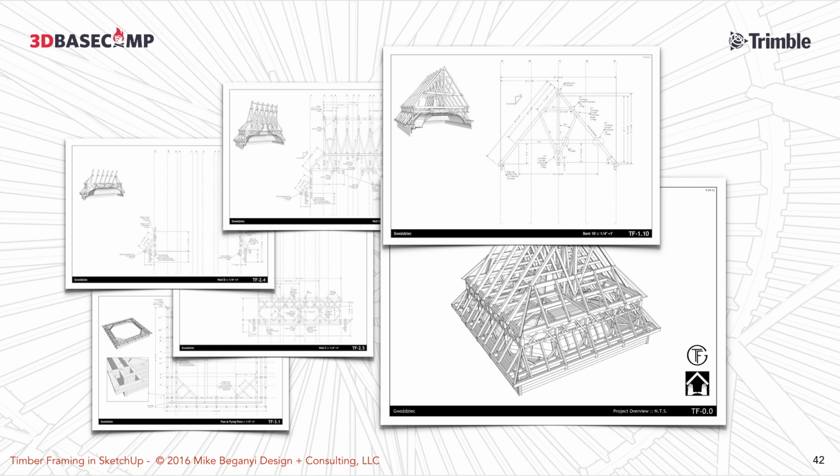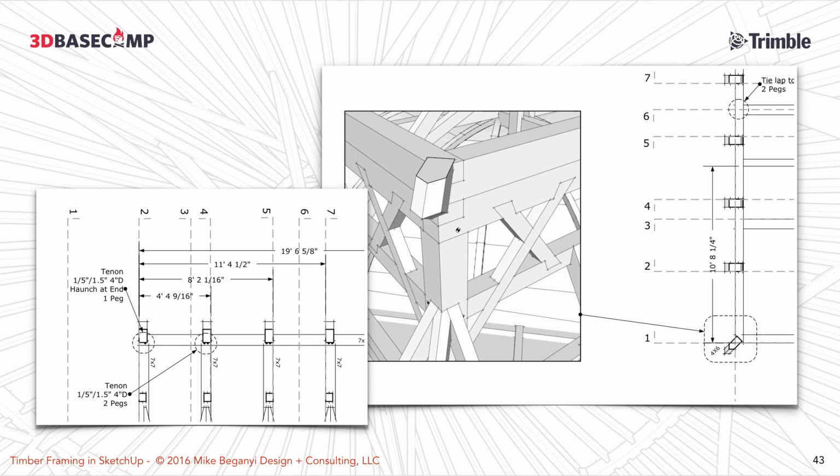So each section of this building had a cut through it, and then I would detail that, and I would also pull off small 3Ds and stuff them into the corner of my main drawing so that you could see how the rafter dropped on the corner. Each one of those little numbers there, 1, 2, 3, 4, 5, 6, 7, I think there were 12 bents going one way and 12 going the other way, because this whole thing is an intersecting roof. Each one of those represented a section cut in my SketchUp model.